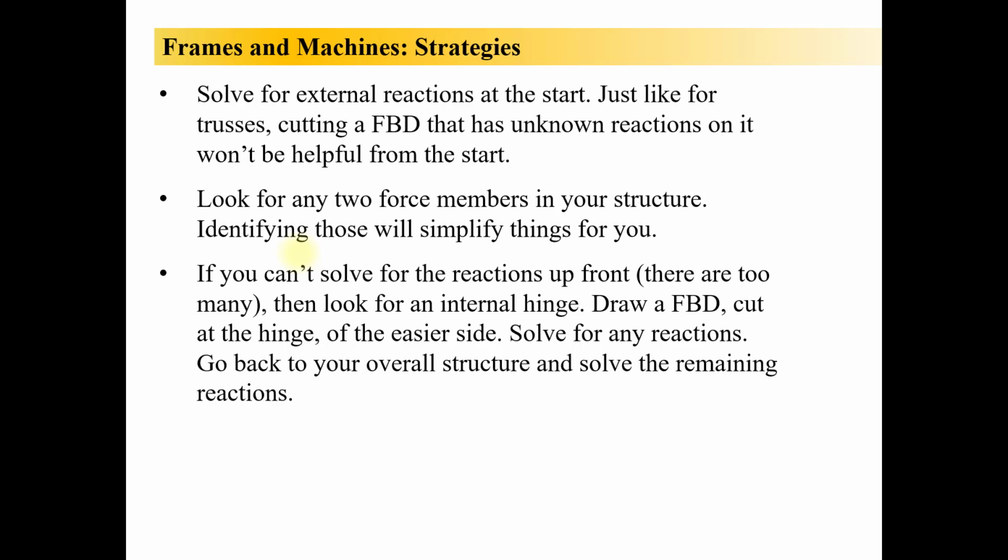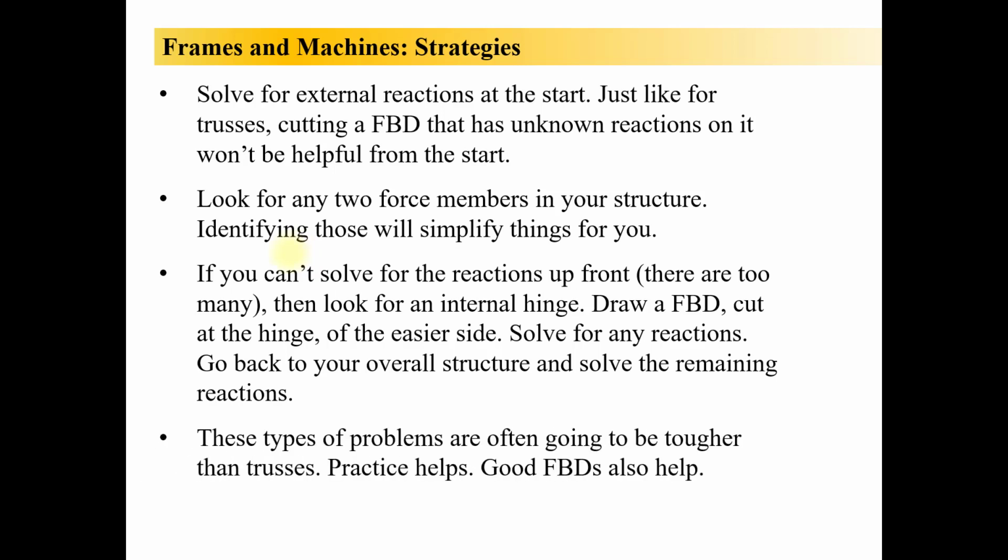And you can draw a free body diagram with a cut at that location. And that will help you solve for some of those reactions that are on the external structure, because that's a known internal state, and it'll help you dive into the structure that otherwise had too many unknowns for you to solve. Once you have some of those reactions, you can go back to your overall structure and solve for the remaining reactions. And remember, these types of problems are often going to be tougher than trusses. Just doing a bunch of practice would help you. And remember to always draw really good free body diagrams.